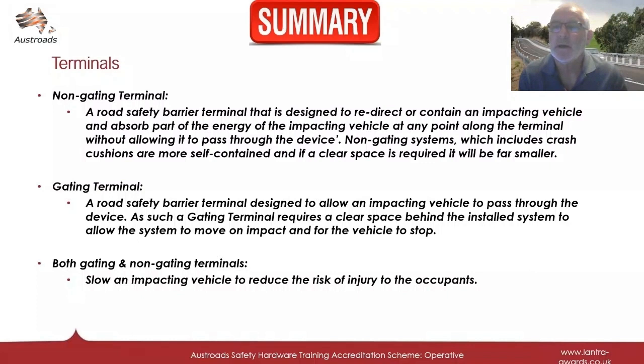Gating terminals: a road safety barrier terminal designed to allow an impacting vehicle to pass through the device. As such, a gating terminal requires a clear space behind the installed system to allow the system to move on impact and for the vehicle to stop. Both gating and non-gating terminals slow an impacting vehicle to reduce risk of injury to the occupants.